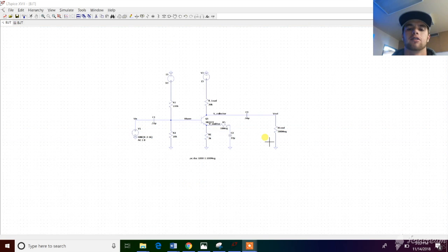So now what we're going to do is look at the cutoff frequency versus the gain, and this is going to be a frequency in which the capacitor is going to act as open, and a frequency where it's going to act as short. So we're going to see what frequencies in which it works.